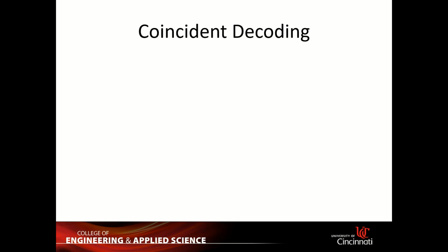So there's a need for a decoding circuit to select the memory word specified by the input address. That means if you have more than one unit cell and a bunch of different memory units, you need a different address for each. You would encode the address in your memory architecture, but then you need to decode the address also. So there's a concept of coincident decoding in here.